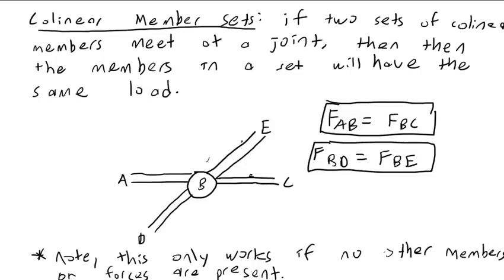So these must be equal and these must be 0 in that axis. If I sum about an axis perpendicular to these, then these will have non-zero force, but this must have a zero force, again in an axis perpendicular to member DE. The book goes into this, read about it there, but that's the basic idea.